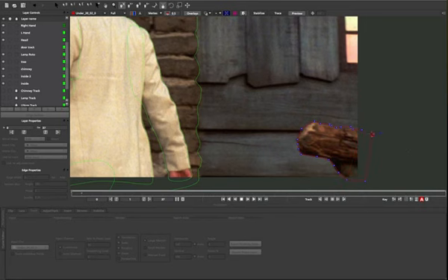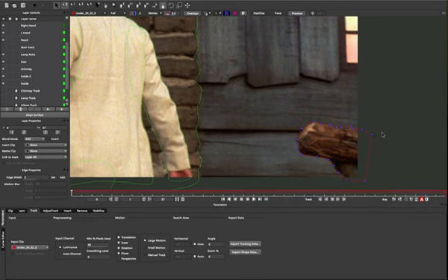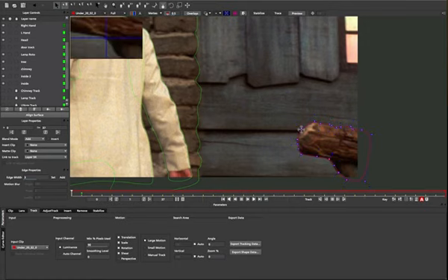Like so. And again, we can be rough around here because it's off the screen. I'm also going to smooth it off a little bit because it's a nice rounded organic object. Now I haven't linked this to a track at the moment because it's in the foreground and I need to track it on its own. So I'm going to do that. We probably don't need perspective here, but I'm going to turn it on anyway. And let's track forwards.